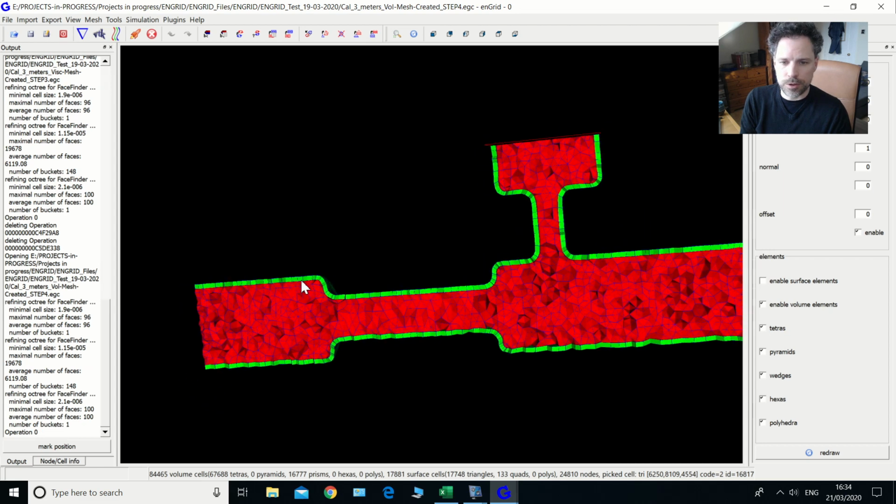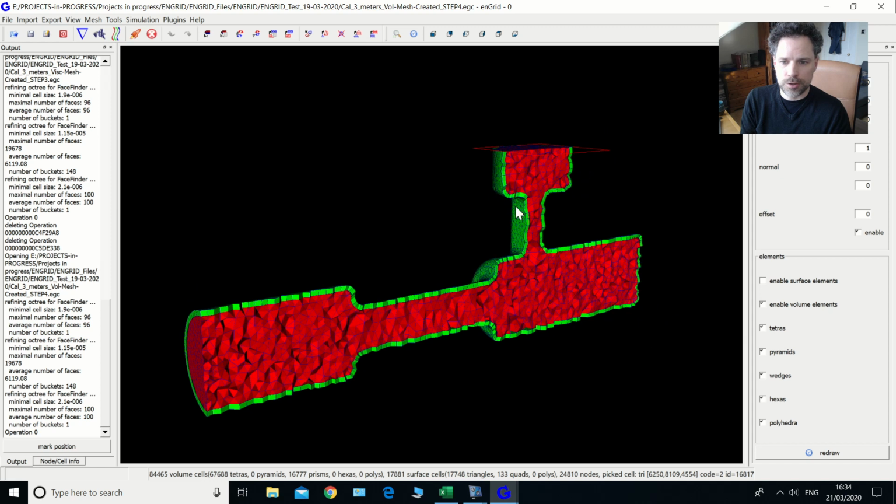So you can see we're getting towards a finished mesh, but we need to subdivide this green single viscous layer into however many layers we want, and to decide how thick the first layer would be, which, if we know what we're doing, we've already decided because we've worked out our Y plus and what we need to have for our turbulence scheme. So that's some physics that you need to sort out for your own model. I've just picked something a bit arbitrary here that happens to work.